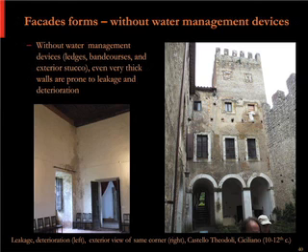So at the far right, when you don't have that, then that gradient just continues to proceed inward, and at the point where that saturation hits the interior, then you have leakage. And you may see free water leakage, dripping. You may see plaster blistering, bubbling, that type of damage, badly peeling paint.